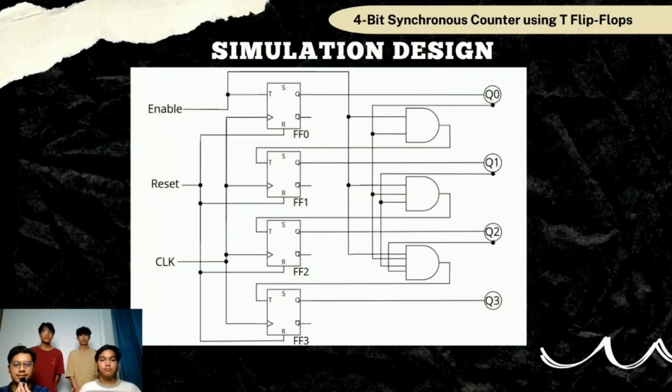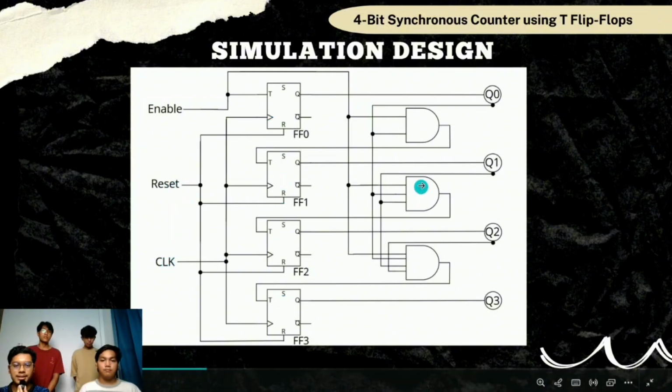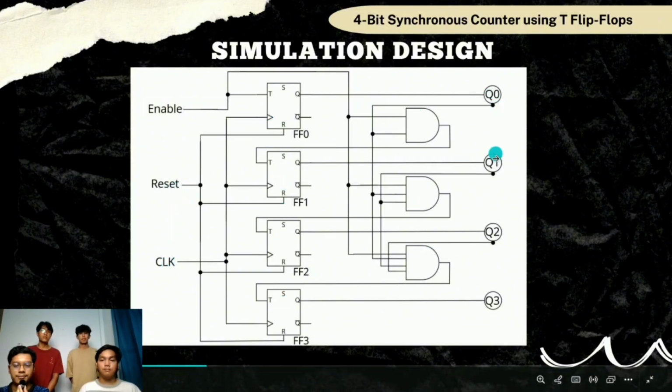Alright, moving on to simulation design for 4-bit synchronous counter using T flip-flops. In our design, we are using enable input pin, reset input pin, clock, and then T flip-flops, AND gates, and lastly 4 outputs.